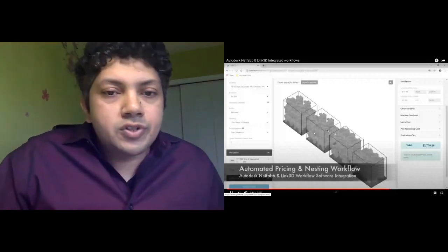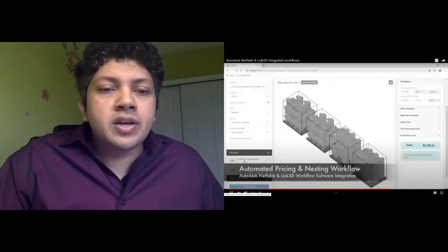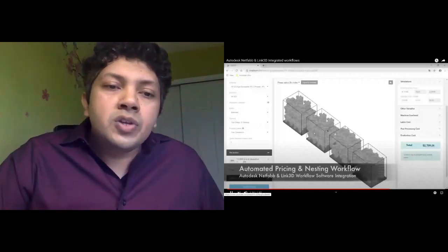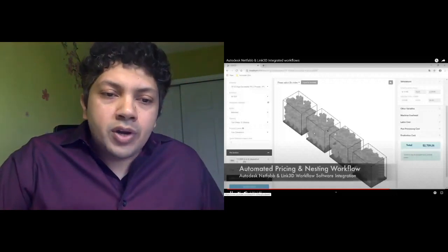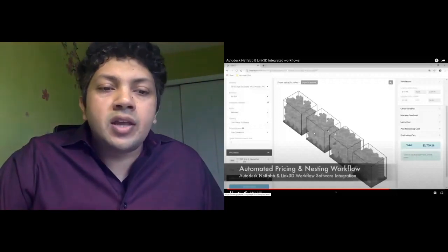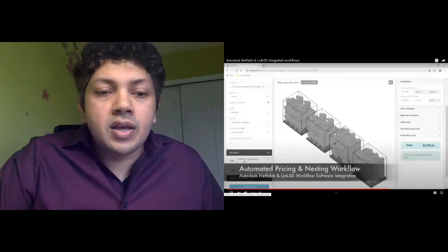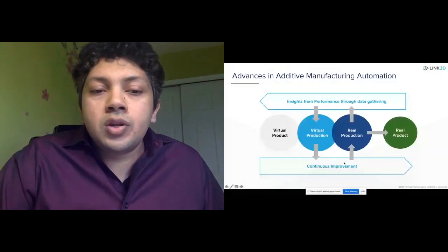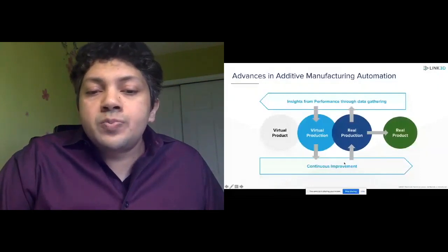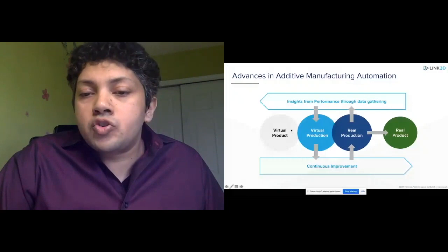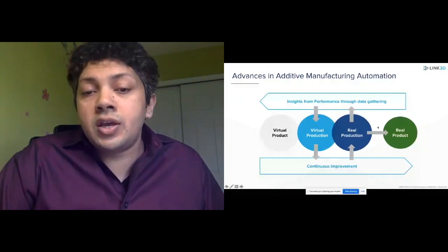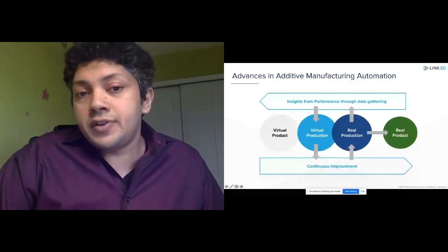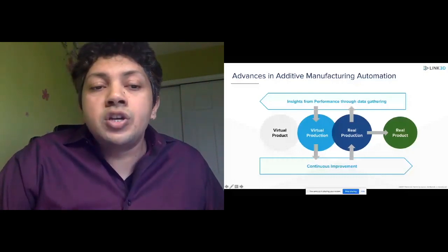And there are several benefits to it. And the final pillar is the advanced algorithms. The idea here is, from the digital realm of production, where the product is virtual, at the CAD, STL or 3MF level, there is a feedback loop of continuous improvement where the digital realm is providing data to the actual production, for example, in orientation, and the feedback from the production, like surface roughness, comes back into the digital realm.